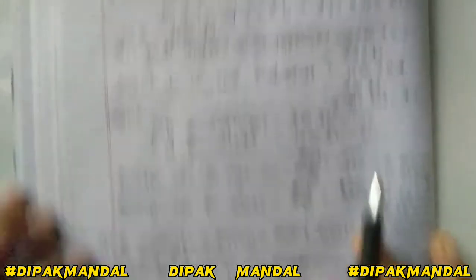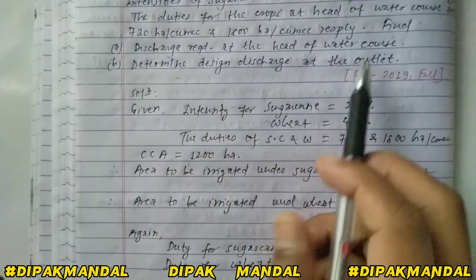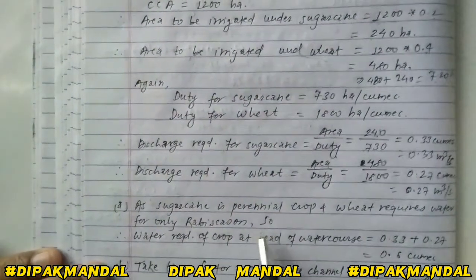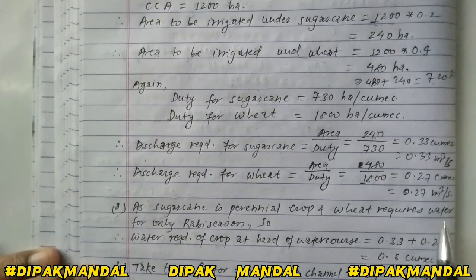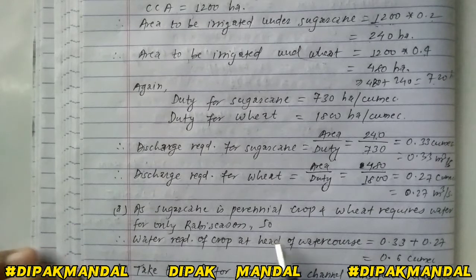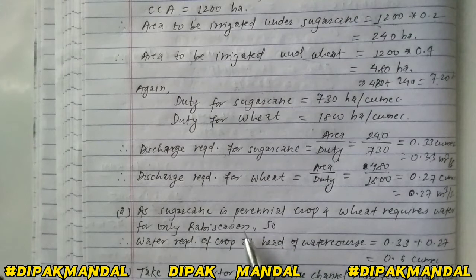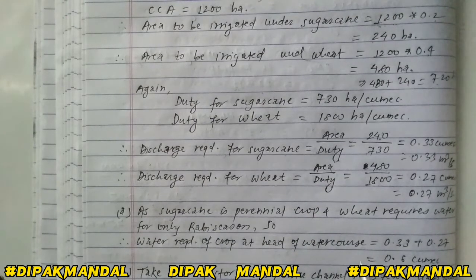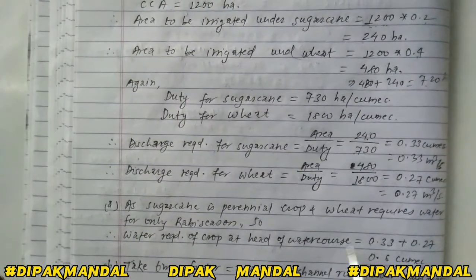Now we have to determine the discharge required at the head of water course. As we know, sugarcane is a perennial crop, and wheat requires water only in the rabi season. Sugarcane is a perennial crop, and that's why, for the water required at the head of water course, we simply have to add these two values.